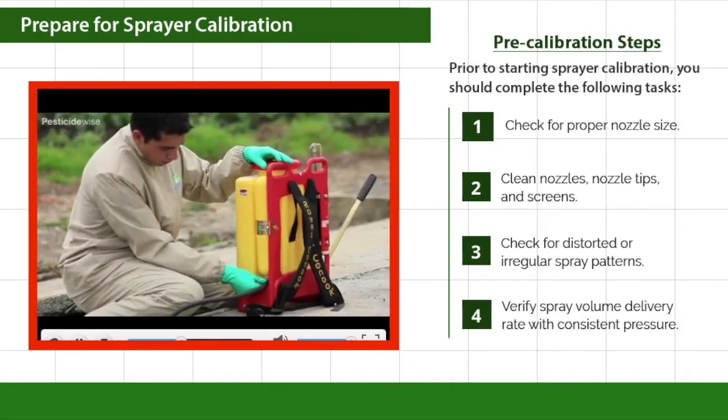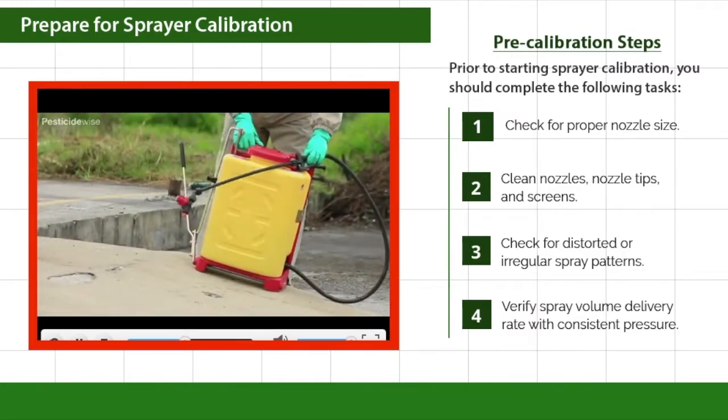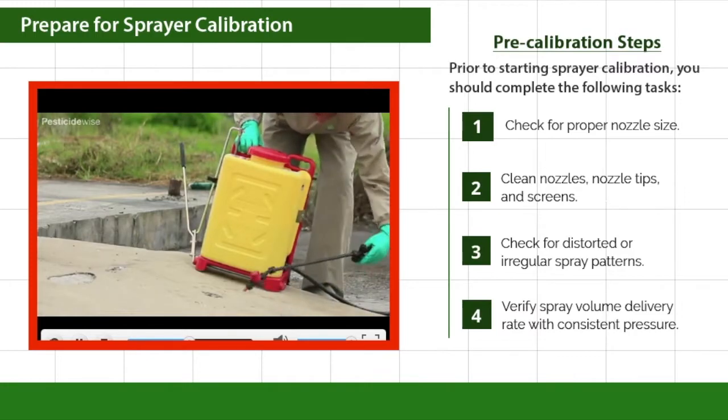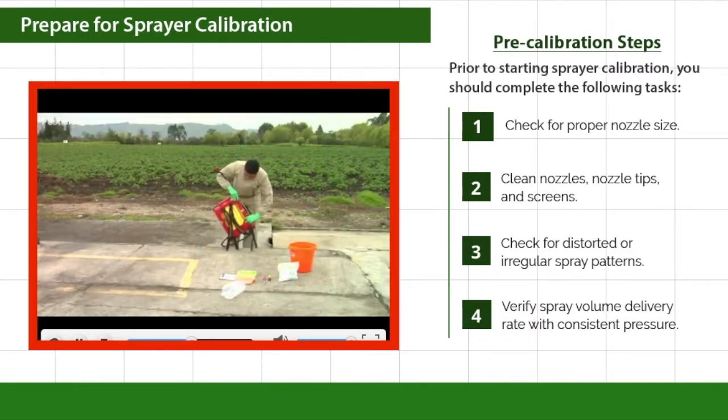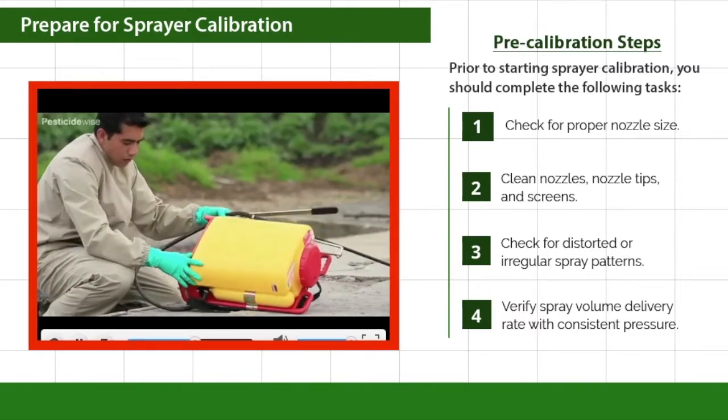With the sprayer upright, check thoroughly for any leakage. Now place it on a slightly inclined surface. If the sprayer falls over easily, then it must be repaired or replaced. Now turn the sprayer onto its side and check for leaks. Then turn the sprayer upside down and check for major leaks.